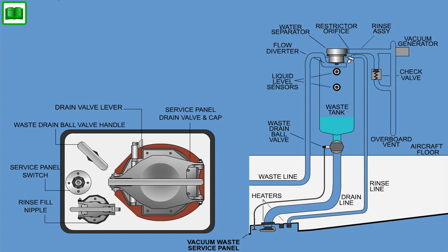Clean the surface of the panel to remove spillages. Close and latch the service panel door. Mechanical stop devices on the service panel door will not permit the door to be closed if either of the valves is open or if the drain cable is not fully seated. One stop device enables operation of the system by closing the service panel door switch contact.